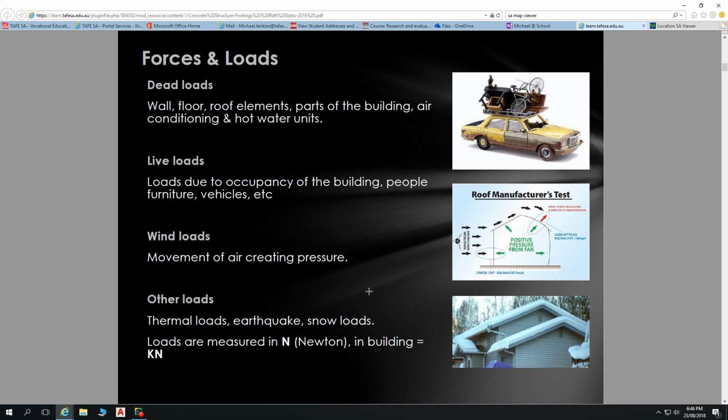So your standard sheet bracing has about 3 kilonewtons of restraint per linear metre, you can increase that to about 6 kilonewtons per linear metre by having rods going through. So that's what wind is doing on the building. It's trying to elongate it, and our bracing reacts to that.